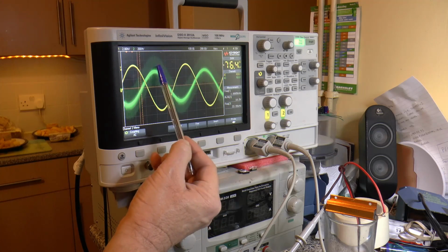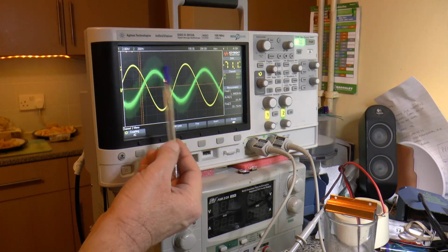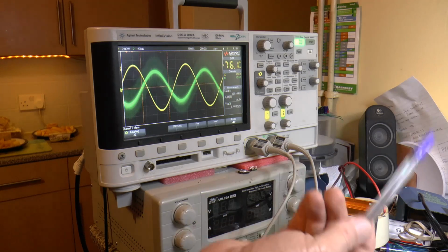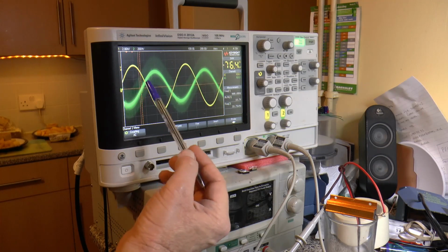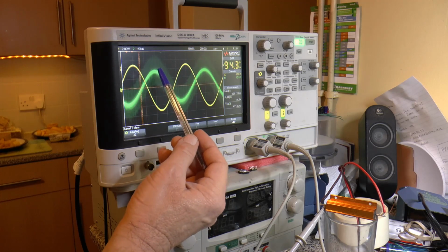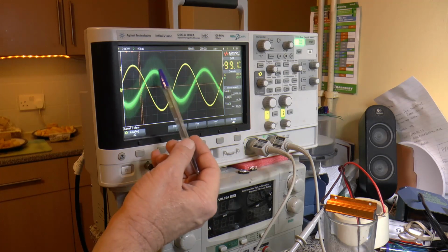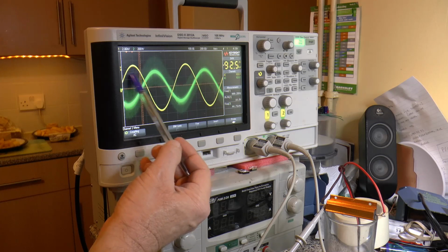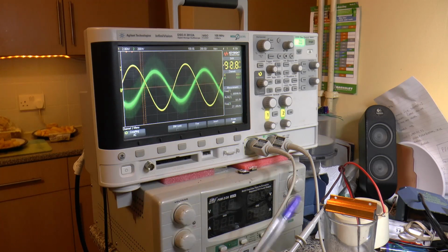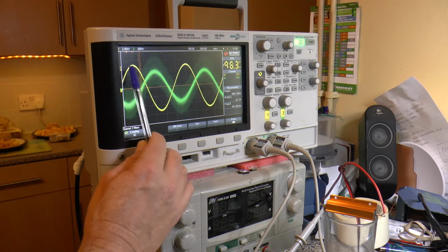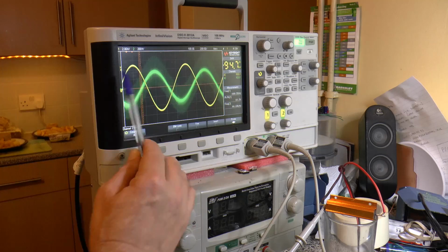This noise here is actually the jitter on that Analog Devices crystal. Nothing to do with Analog Devices, it's the crystal on that cheap board from eBay. And the treble is quick enough to see the jitter. The bass, having a lower frequency response, isn't. So yeah, Mackie amplifiers, they've taken out a couple of op amps and reduced the delay.